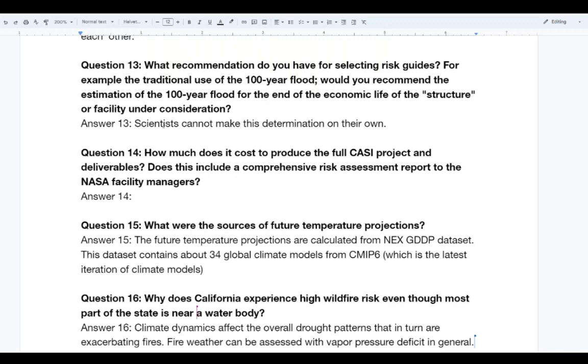Of course, if you've looked at probabilities and understand the definition of a 100-year flood, it does not mean that it happens exactly one time every 100 years. And it certainly does not mean that it won't happen until 100 years from now. We've seen many examples in recent years of events that people thought were 1 in 100-year storms happening multiple times in the same decade. That can happen by chance. It can also happen more frequently when the statistics themselves have changed.